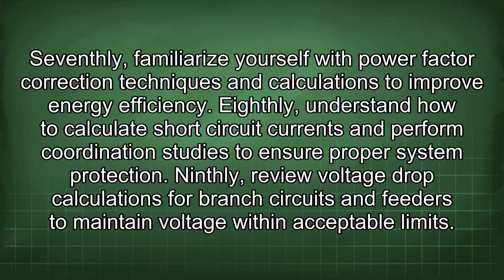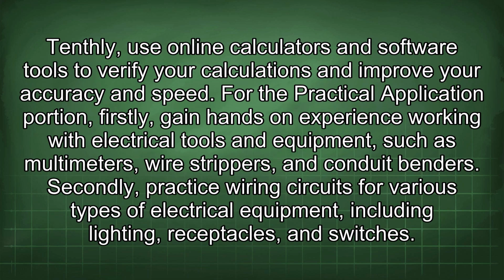Eighthly, understand how to calculate short-circuit currents and perform coordination studies to ensure proper system protection. Ninthly, review voltage drop calculations for branch circuits and feeders to maintain voltage within acceptable limits. Tenthly, use online calculators and software tools to verify your calculations and improve your accuracy and speed.